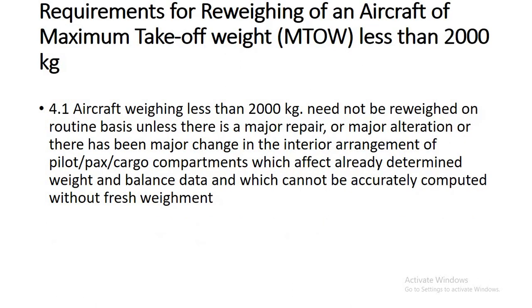Next, for weighing purposes, if your aircraft's maximum takeoff weight is less than 2000 kg, then you don't need to conduct a routine reweighing of the aircraft, unless you do some major repair or major alteration, or you have changed the interior arrangement of pilot, passenger or cargo compartments which can affect the already determined weight and balance data, and that change cannot be theoretically calculated, then you have to do a weighing. Else, in normal operation, you are not supposed to reweigh an aircraft if it is less than 2000 kg maximum takeoff weight.